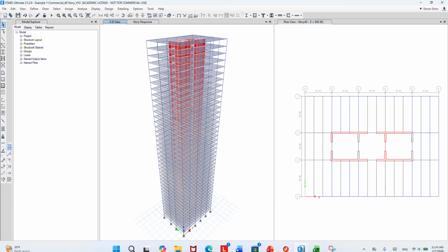So by looking at it, as I said, we have two choices. Okay, can we continuously increase the wall thickness and concrete strength? Or let's think about considering outriggers, because we have upper portion deflection that is a little bit exceeded. So if we add a couple of stiffness, maybe outrigger might be more efficient.